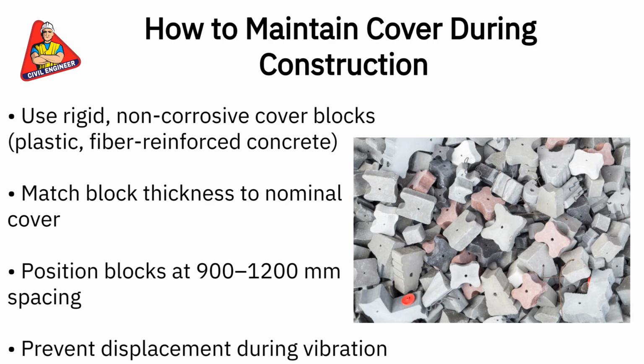Always use non-corrosive cover blocks of appropriate thickness, aligned with design drawings. Blocks should be placed at 900 mm intervals along rebars. Use chairs and spacers for slabs and walls. Concrete pouring and vibration must not displace reinforcement. Proper tying and stable formwork are essential to maintain cover tolerance.